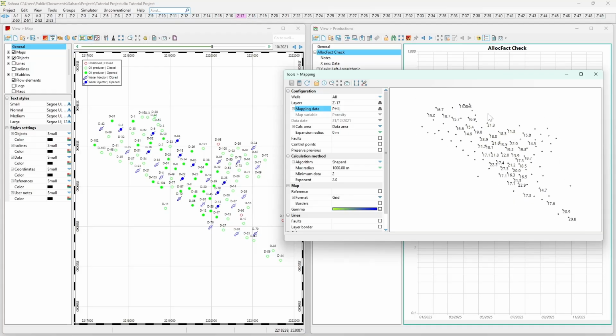which is the value associated that is going to be mapped for this variable, porosity. Something that happens and is quite common, especially when you are plotting tops, is that you will select everything like this, and you will see your wells without any value in them, even if you know that you have a top associated. The cause of this is that you don't have any datum loaded in the project, which means that there is no way to convert from the MD in which the tops and bases have been imported most commonly into the TVD sub C in a common reference point, because you need to import the datum of each well.